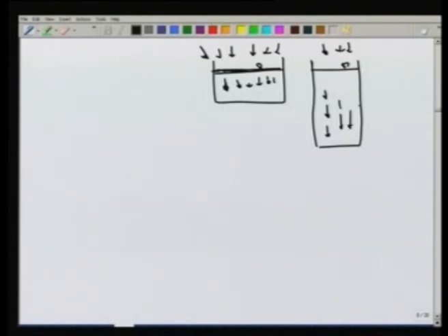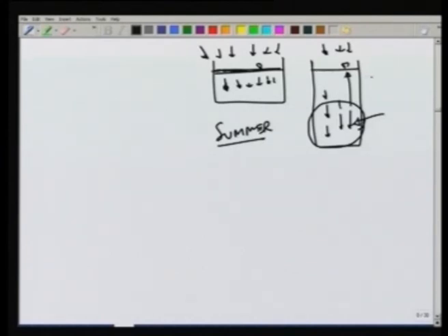So, in summer months when there is high radiation, the water here at the lower level will absorb the radiation, and in winter this radiation will be released to the upper layers to cause evaporation. So, in summer the shallow body will have high evaporation because the absorption by the lower layers is not there.